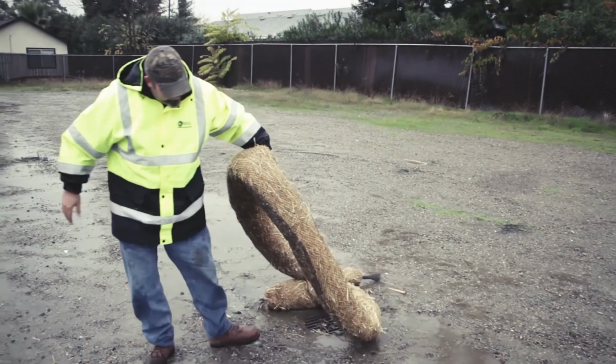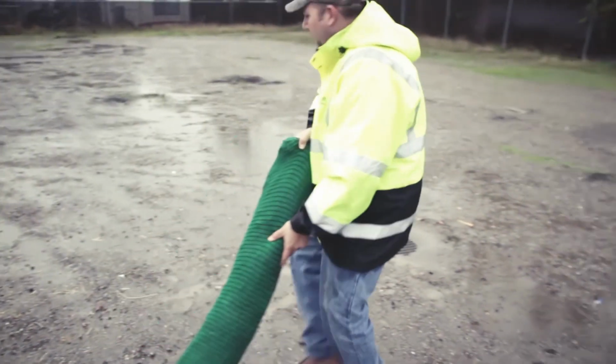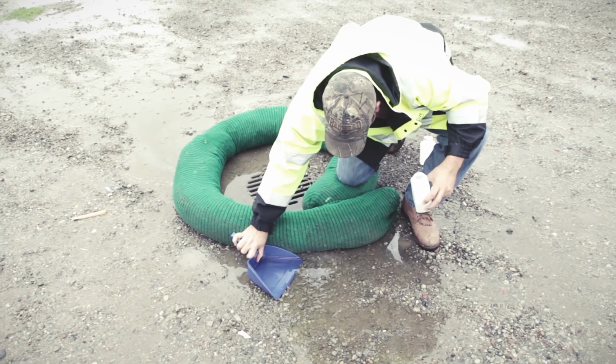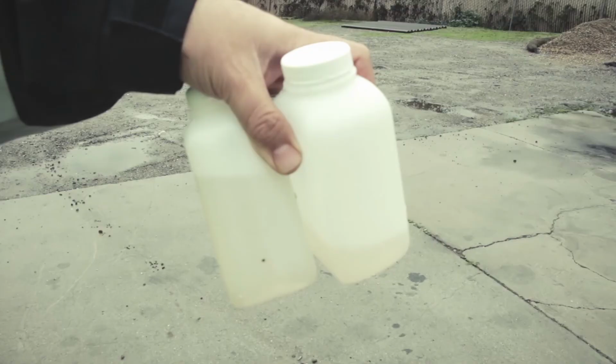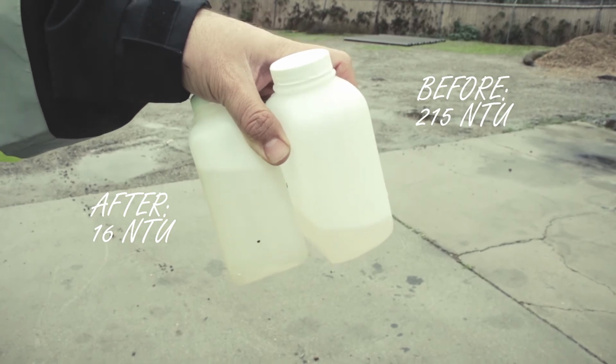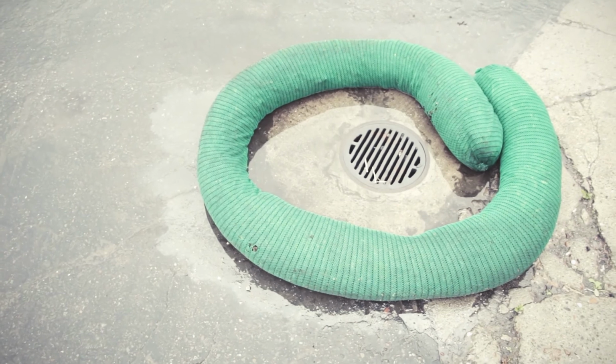We then removed both fiber rolls and installed compost filter socks around both drains. After waiting another 30 minutes, we returned to the drains, and the difference in filtration results was remarkable. The water in the gravel lot was much cleaner, well within NAL limits. The parking lot water was filtered clean as well, and the sheen was completely removed.